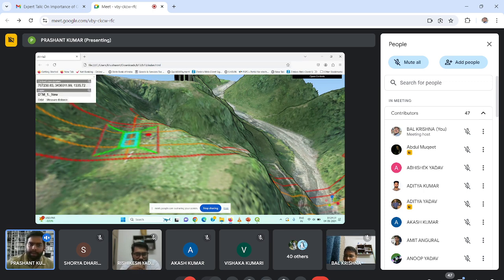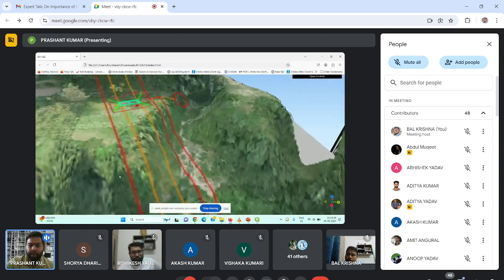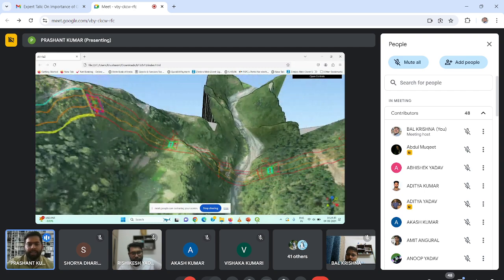The coordinate system is UTM, the global coordinate system I have set in. So I can directly visualize in the global coordinate system. If I want to share coordinates with someone, like go to the site, tell the surveyor, if I'm seeing that this point is not good, I have to shift this foundation a bit below, I'll just share these coordinates. You just go to this coordinate, put an offset at site, see what features you are having, and whether it is matching or not. And now comes the next situation.